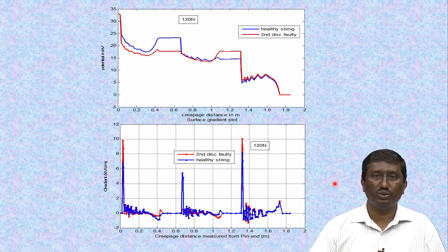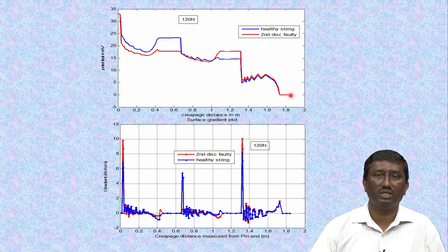So, we have tried to see the potential behavior or performance, and we start with the example of a simple 3 disc insulator string. So, 3 discs, each you can see one disc is connected at 33 kV, intentionally 33 kV potential is applied. You see the 33 kV potential, and second is at 20 kV or 22 kV, it is not uniformly distributed, and the third insulator is here and the cap of the third is connected to the ground end.